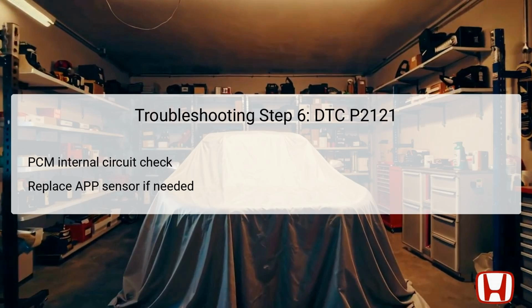A successful match would direct the technician to access any authorized service information that may assist in resolving the DTCs or symptoms present. If successful, substituting a known good PCM may indicate a fault with the original unit. If all conditions are met and the errors persist, replacing the APP sensor module becomes necessary for resolution.